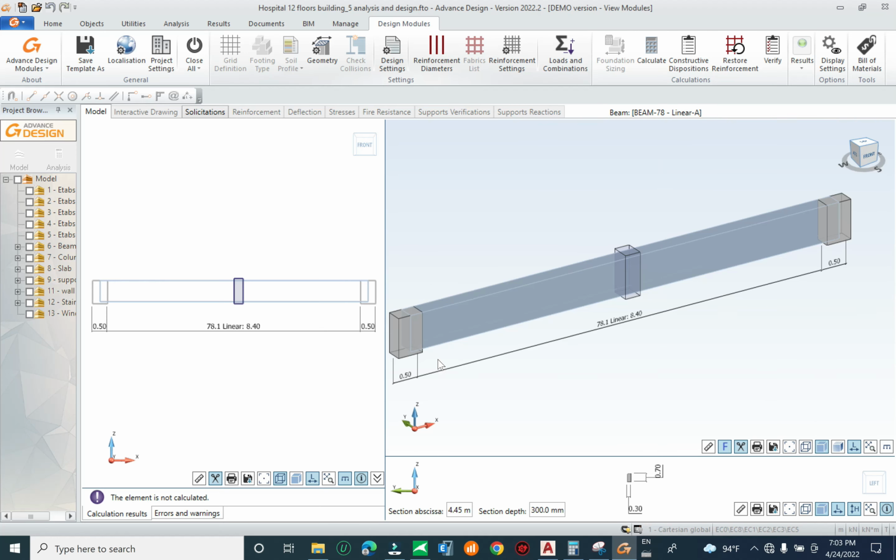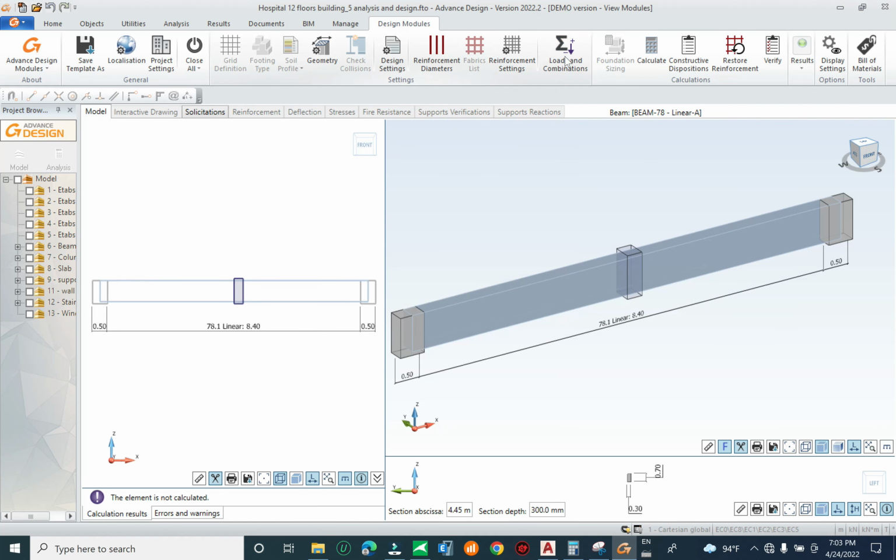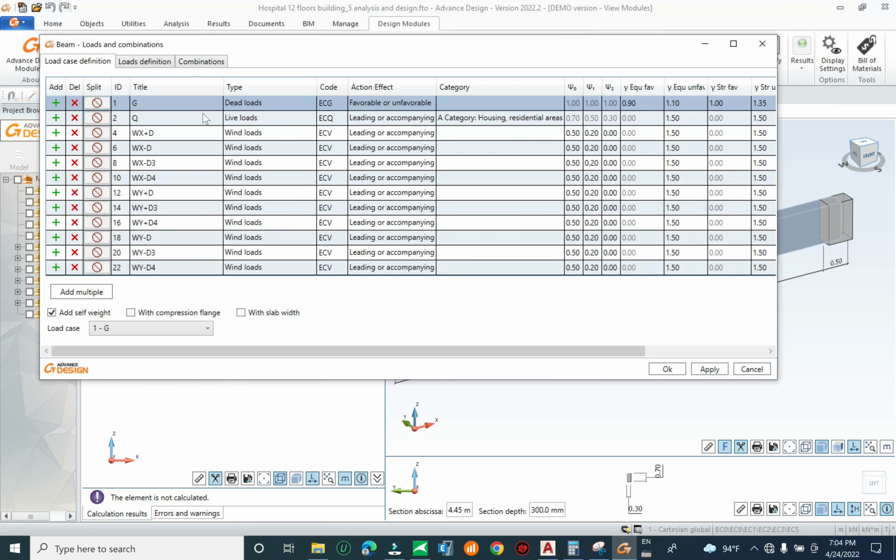This beam you can design to receive the gravity load, and for the lateral load include wind load. If you design for the vertical load only, you cannot design it for the horizontal load. But in this system, you have to design it for both gravity load and lateral load, because your beam also receives wind load, connecting one column to another column to make a system of moment connection with each other. Okay, to make your structure stable, your beam also receives and is designed for the lateral force.